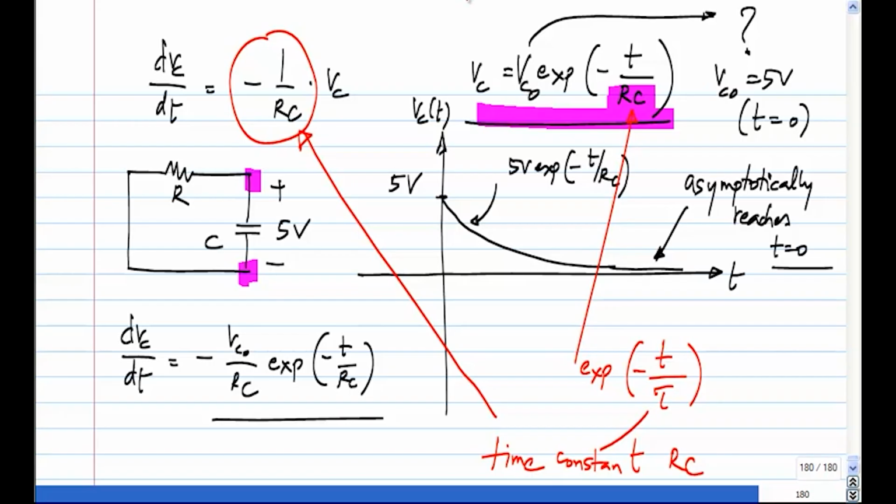And it's very common to hear terms like Rc time constant of a circuit. So this is what it is. It influences the rate at which this falls. What happens if this time constant is very large? What happens to this curve? Will it fall quickly or slowly? Slowly, right? Because if, let's say, R is very large, I mean the time constant could be very large by the R being very large or C being very large. If R is very large, what it means is that the current is very small. Initially, for the same 5 volts, the current is much smaller. So that means that it will discharge the capacitor lesser.